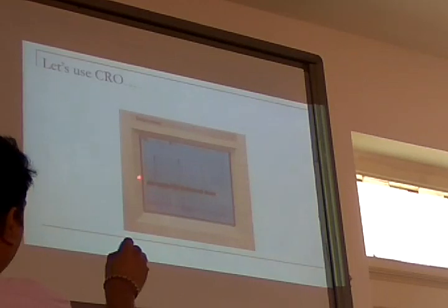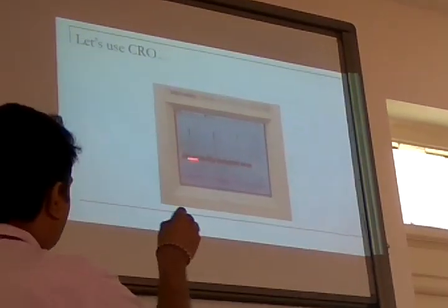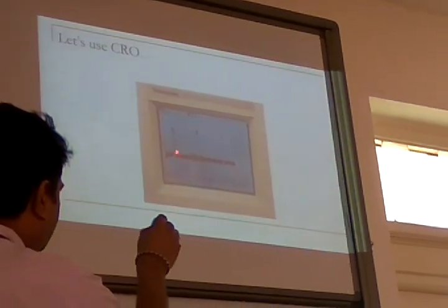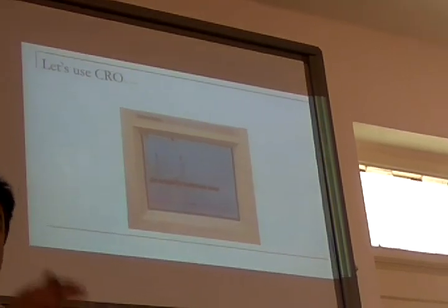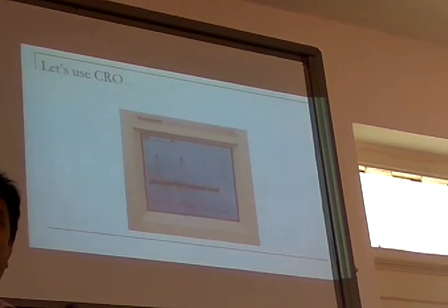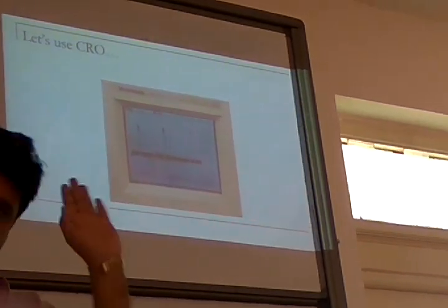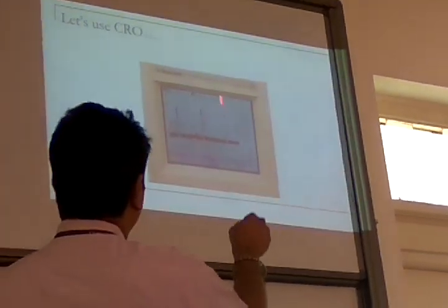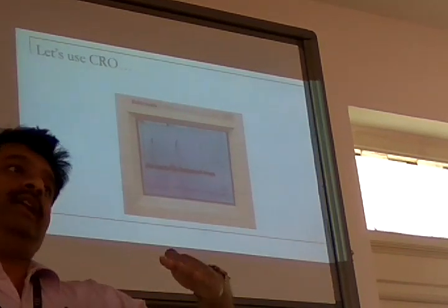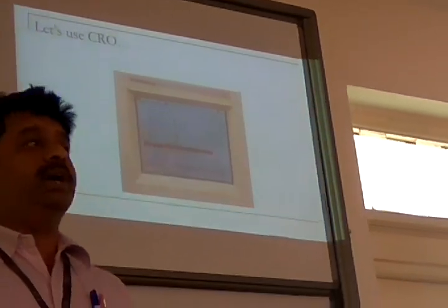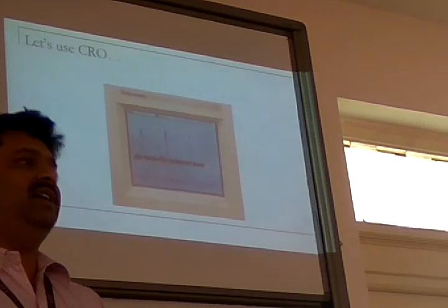Put the link down. This RMS value. So I am expecting a constant DC signal. Even if there is a small white noise, while taking RMS, that plus and minus component may cancel, and I'll get more or less close to the actual value. Still the error will be there, but the error will be less. But if you see the peaks are there, or as I told you, 50 Hz signals are there, the RMS value is boosted compared to the DC value that we are interested in.